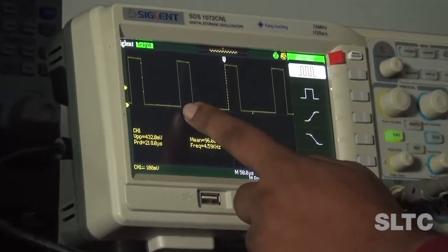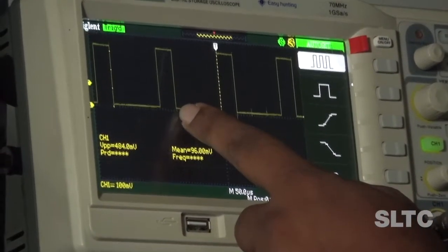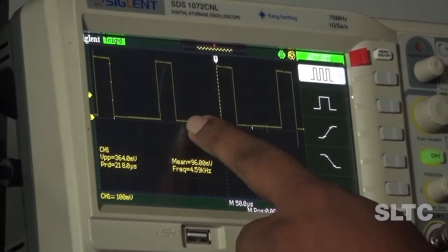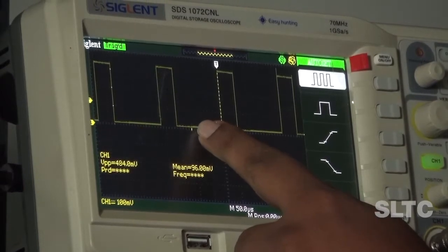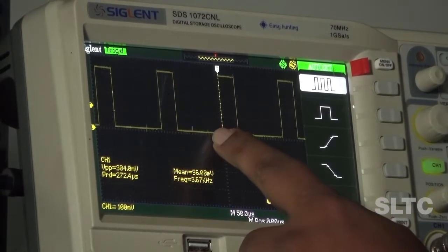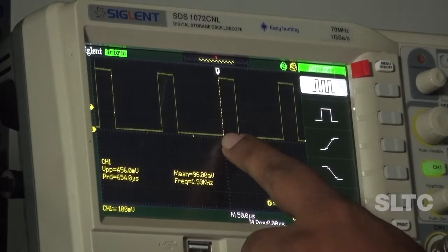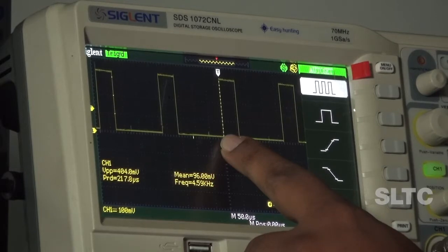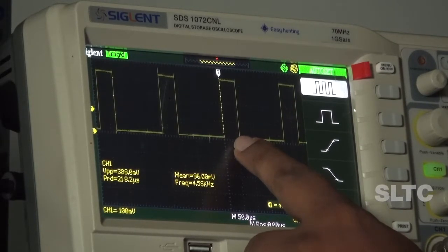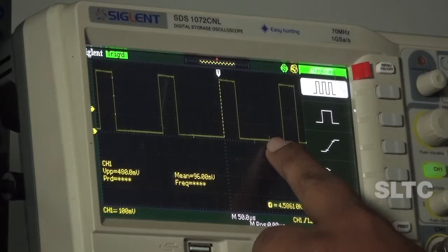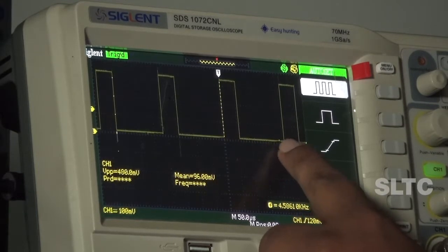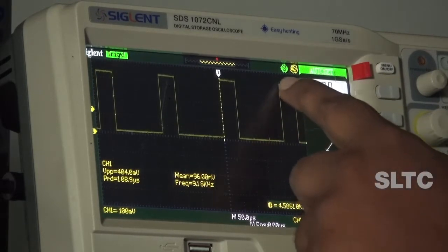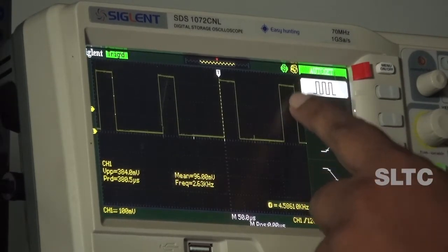the multiplexer will read the first information. After the address bit changes after some particular time, it will read the second user, third user, fourth user, and this is the fifth user information, and for the fifth also I have given a 1 value. So, it will read it. Okay. And the seventh user, eighth user, and so on it reads; there is no information, and after that it again reads the first user information, first port.